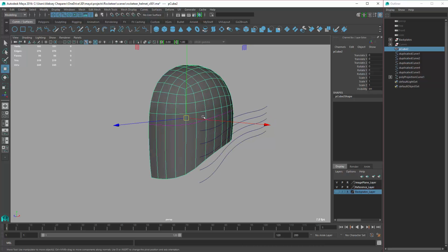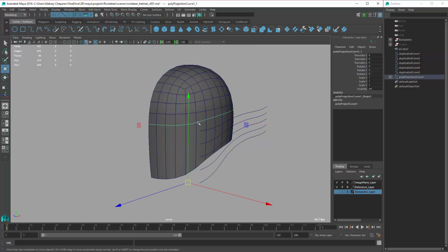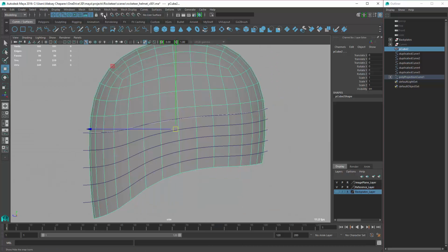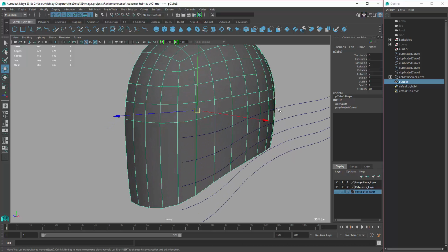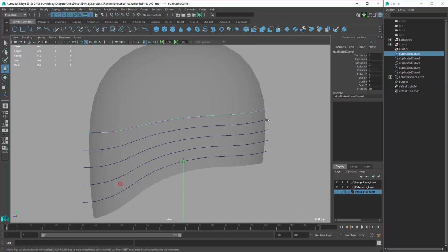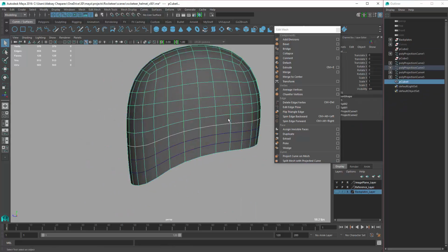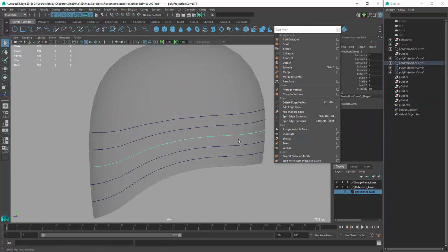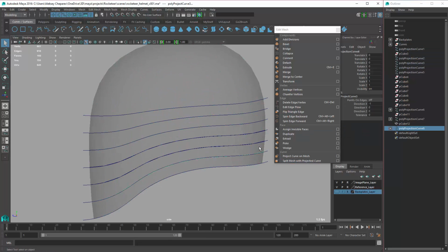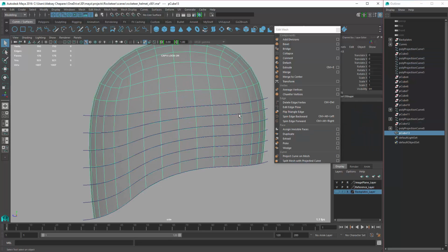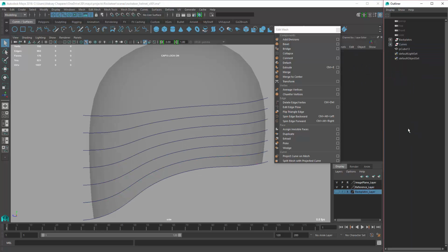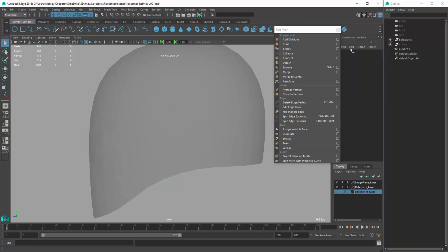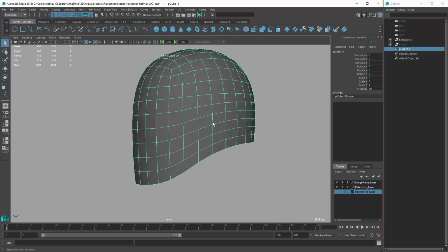So now we have this curve. I'm going to then select the curve and then the mesh, and then go back in here and click split mesh with curve, and now you can see we have a split mesh, and then we repeat. So let's clear history. Let's see, we don't need actually these curves here. All of this is garbage, and this would just hide, and it's going to be a little messy.